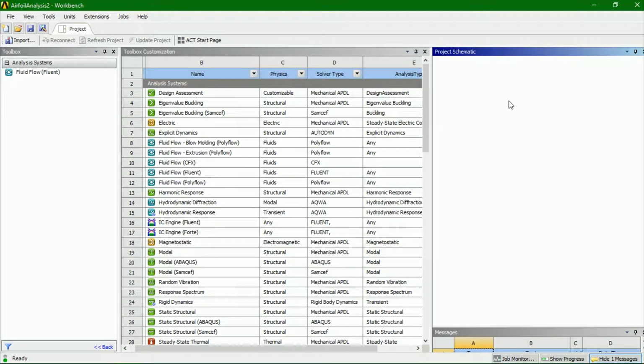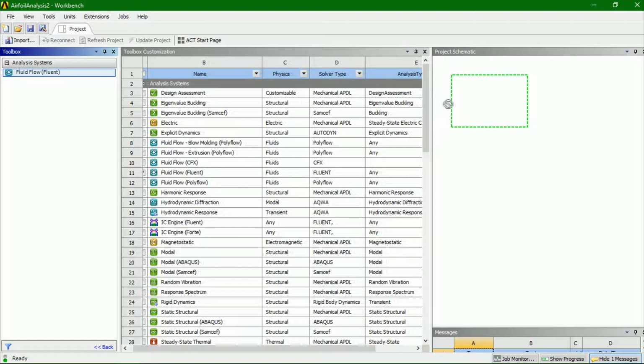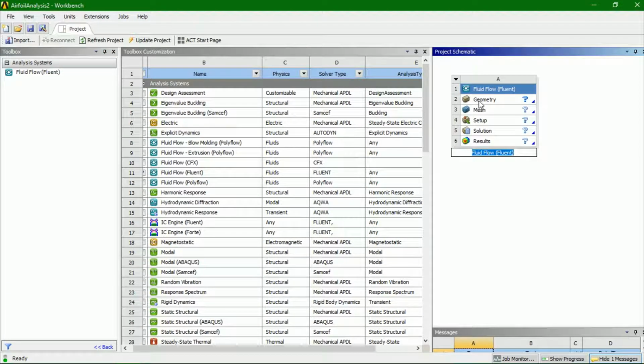Hello, we are Jose and Alex, and today we'll be showing you how we do the ANSYS analysis of a given airfoil. So we have already done the airfoil in CATIA, and now we are going to import the model into ANSYS. The first thing we have to do is to create a standalone system, and we name it, for example, airfoil. We enter the part of geometry,